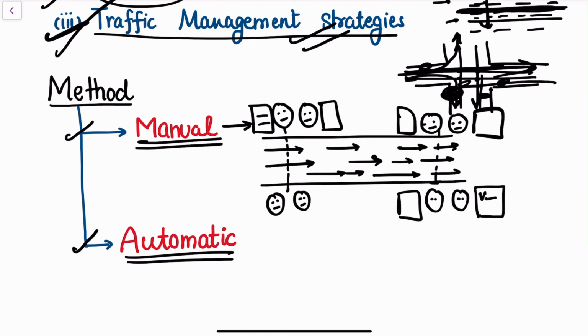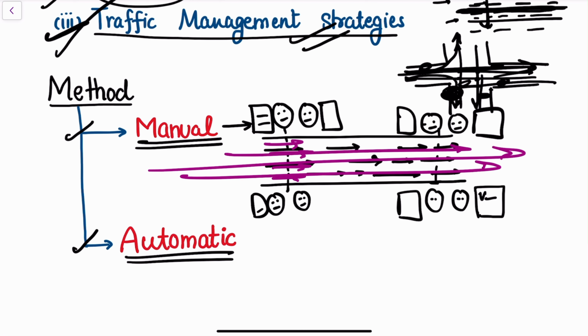The reason they match their data logs is that multiple vehicles can cross the section of road at the same time, and many times fast moving vehicles cross the road. Since humans are involved in the recording, there is a high probability that some vehicles may be missed by some surveyors. So at the end of the day, they match their data logs, and from there they get the average value of the traffic that is moving in the study section.